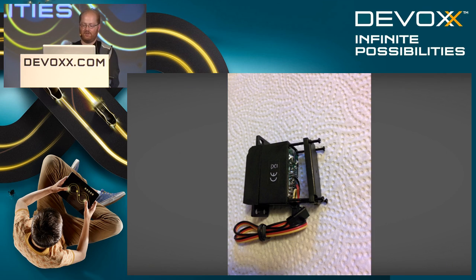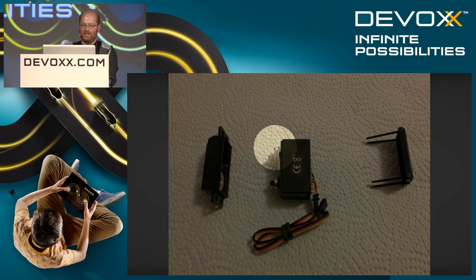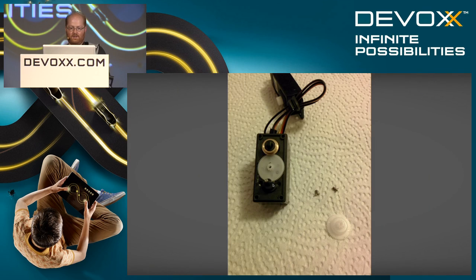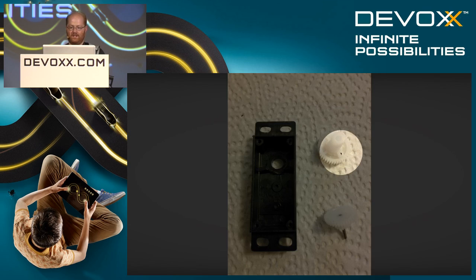So you just open the servo, then you see the gears here, and here's some resistor that we have to pull out. So the problem here is that this gear blocks the rotation to make sure the resistor won't break.